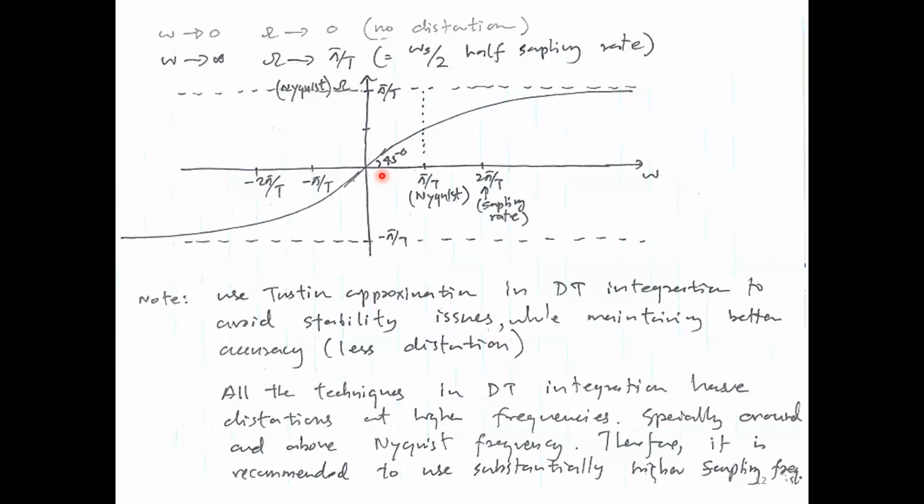Now, how can you go for 1/4 of Nyquist or 1/3 of Nyquist? By selecting the sampler, right? You select a sufficiently fast sampler, so then your Nyquist is high, your quarter Nyquist is also high. Understand? So the determination of the sampler, the sampling frequency, is very, very critical, therefore. And it can solve a lot of problems in your digital control system. So if I can name one single piece in the discrete control system which is most important, I would pick up the sampler, definitely.